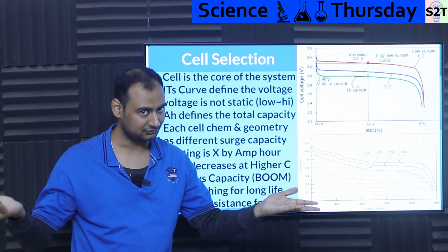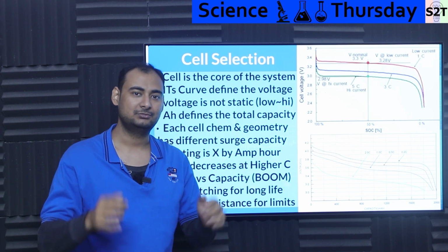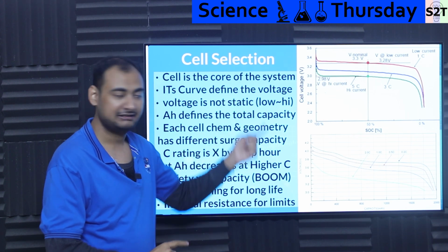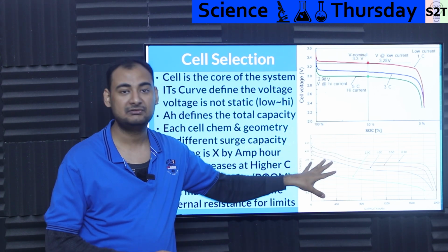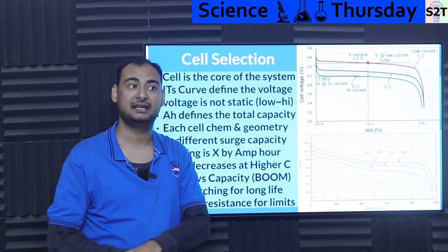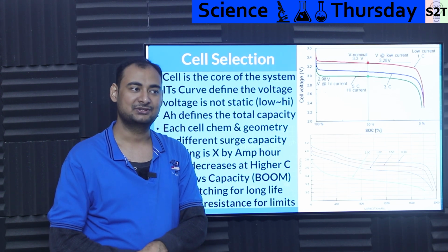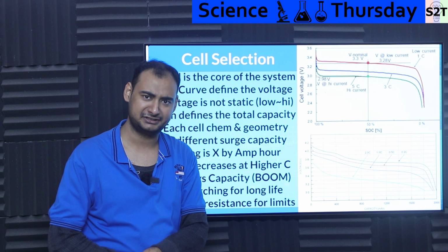Now, not for 1 hour, of course, but at 50 amps it should be safe and should not overheat within the temperature limits. Again, they will never tell you; these ratings are always standardized to 25 degrees Celsius. I have no idea why. And if you are designing anything for India, please look into the graph, because India is hot. Focus on the 50 degrees Celsius graph.